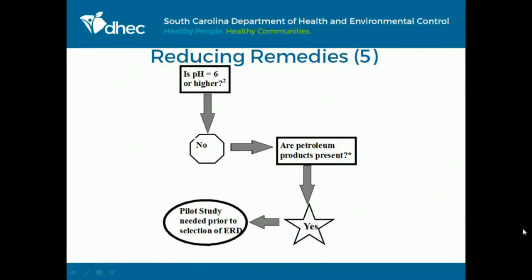And I believe this is on page 12 as well. Is pH 6 or higher? No. Are petroleum products present? Yes. A pilot study may be needed prior to selection of reductive dechlorination.